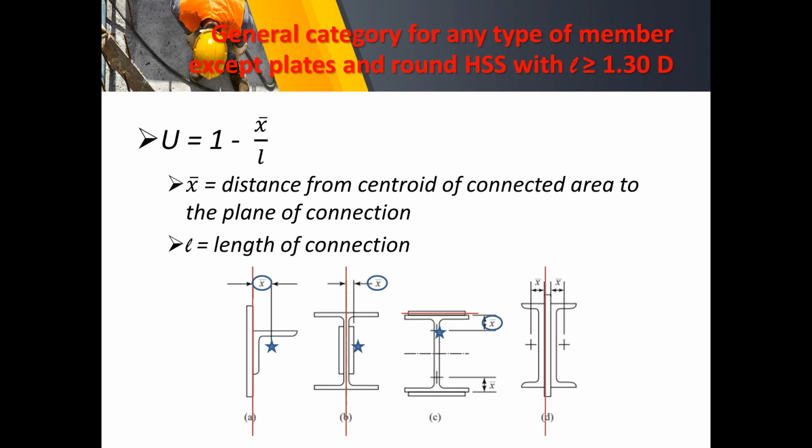Finally, for the built-up channel section, this is the plane of connection from the plate along one side, or the left side, of our channel bars, and hence this is the centroid and the X bar. I think that plane of connection shall be adjusted towards the right along that side. Okay.